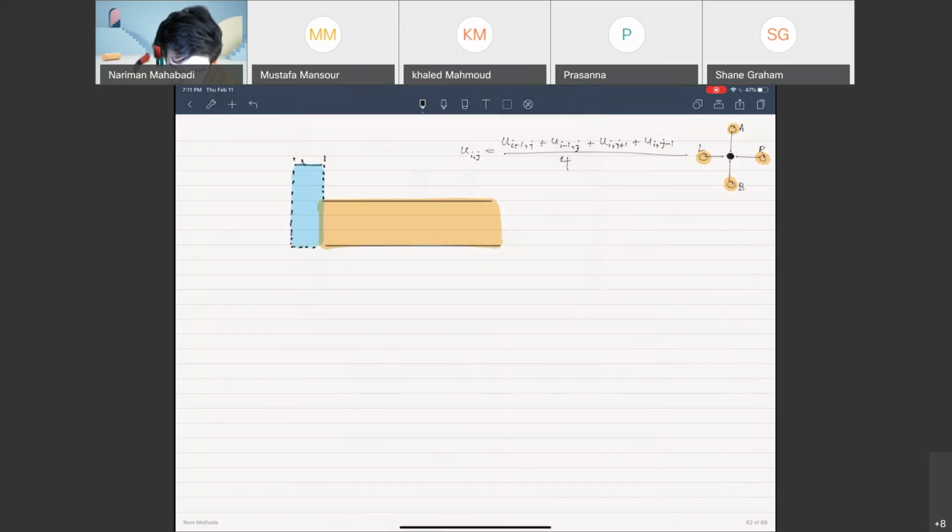So in this case, let's say this is the total head from my inlet, and this is known, right? On the other hand, this is an open boundary. So this is my total head at the output, and this should be equal to 0 because this is an open boundary. The water can freely move out from your boundary, right?